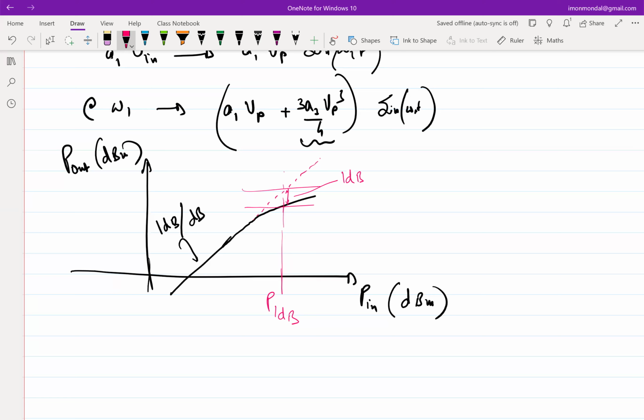So when you see research papers, nobody is going to tell you harmonic distortion, this and that. They are going to tell you this P1 dB is this much, right? From there, you have to interpret whether it's a good number or bad number. So typical P1 dBs for front ends can be anywhere between 0 dBm to 10 dBm to 20 dBm, depending upon the application. So 0 dBm is often an acceptable P1 dB number. But again, you cannot simply quote P1 dB without quoting many other things, but these are some ballpark numbers that you should be aware of, right? I should also write this down.